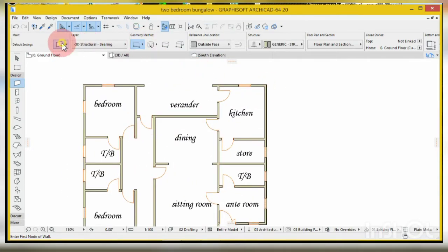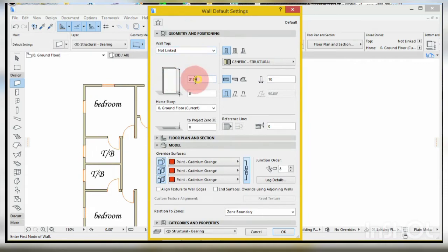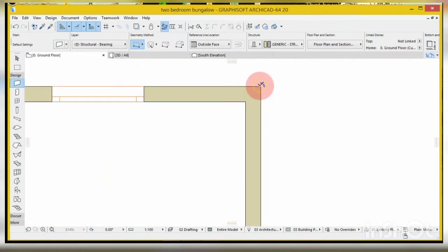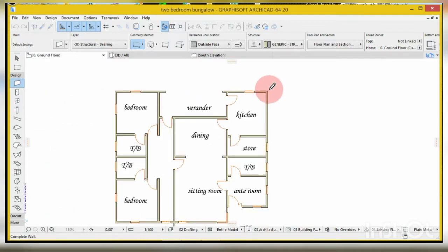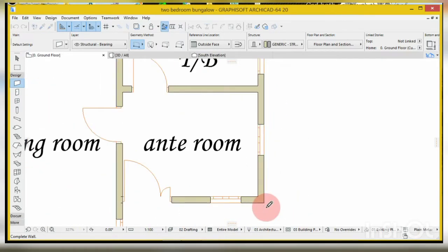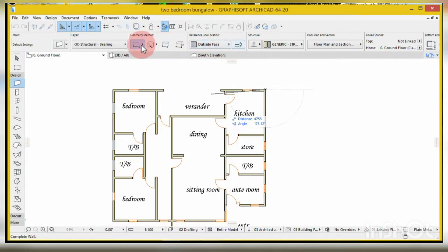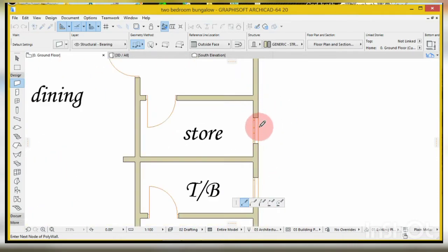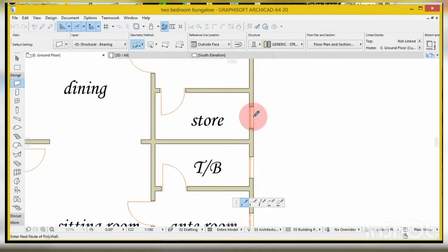Okay, I forgot to reduce the height. This height, I want it to start from ground and then reach where the window started. That was 900. So that is it. I now come and draw. I draw to this point. I like choosing this so that I can be breaking them apart because of the window.